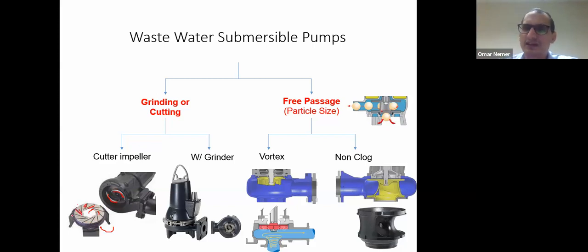There are very sharp grooves. So the impeller actually presses the particles on these grooves, so they will be cut. So you can make these particles smaller, then the same impeller will pump them out.